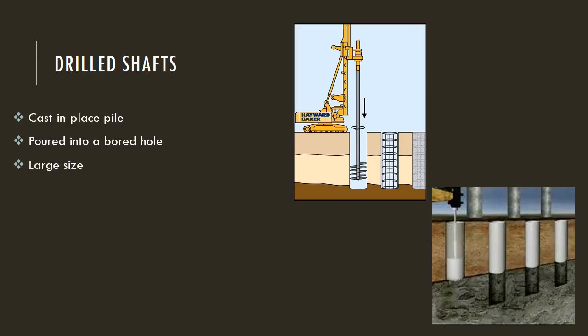They are usually large with diameters of 3 to 12 feet. Because of their large size, the use of this type of pile can often eliminate the need for pile groups and pile caps, which can make it a more economical method of stabilization. The size of the shaft also provides increased lateral force resistance against sliding soil masses. Drilled shafts are often used in urban environments and near highways because the holes can be bored directly into an existing slope without the need to purchase extra right-of-way.